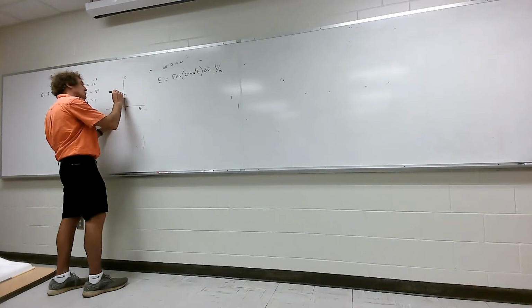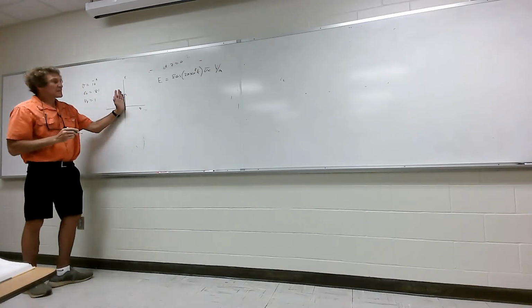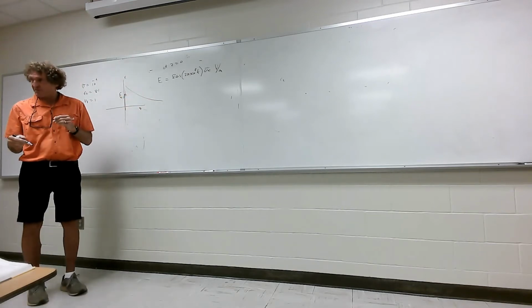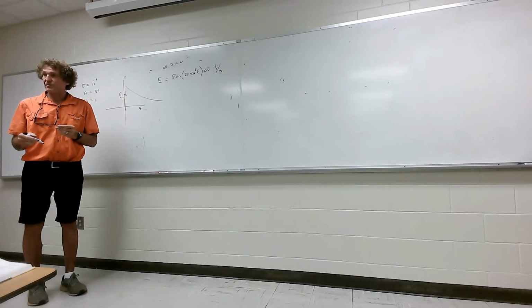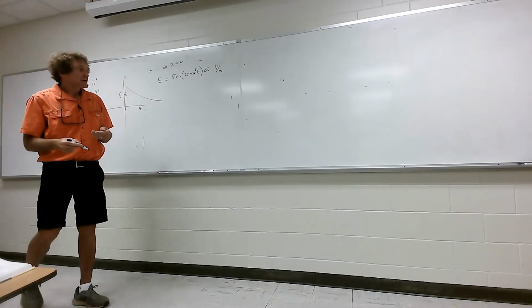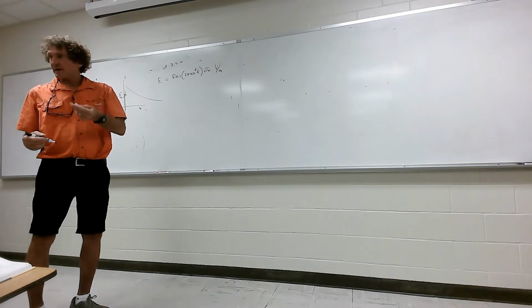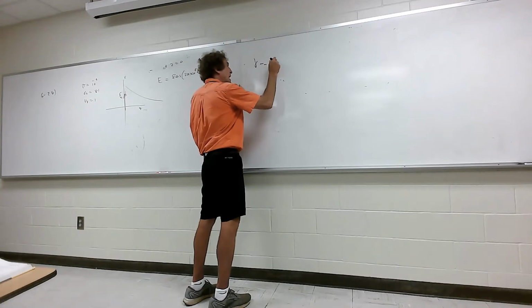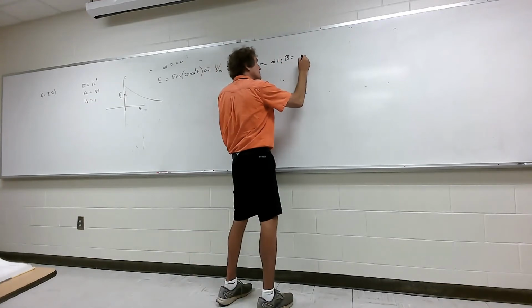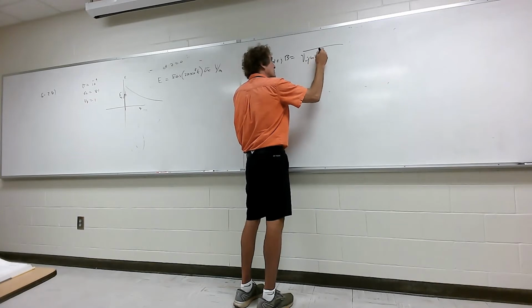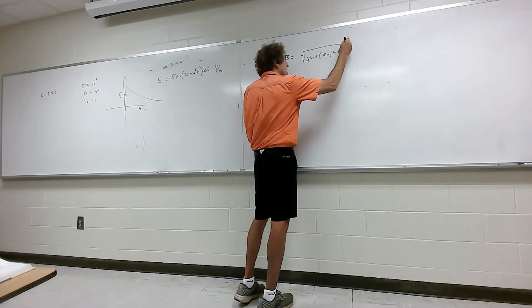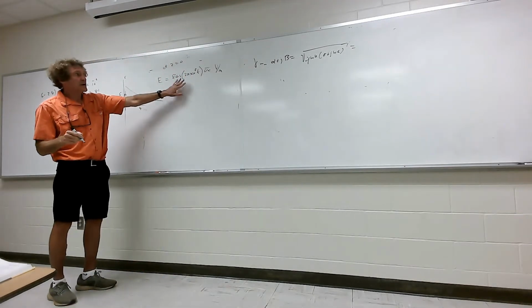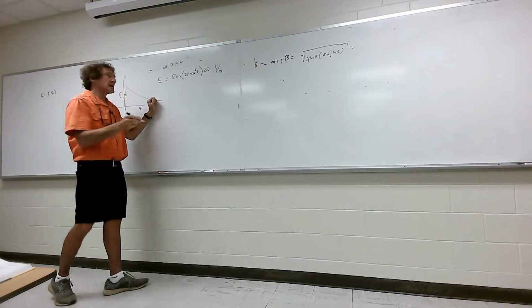The E field is like this, so we have E field versus time at this point. Now they want to know what the actual formula would be inside this region, where the actual distilled water is. Do y'all follow me on this? So what we have to do is get alpha and beta, so we need gamma first. Gamma is equal to alpha plus j beta, and that's equal to the square root of j omega mu times sigma plus j omega epsilon. Now, I'm going to get to this in a second, but looking at this equation, what can you tell me about omega just by looking at it?